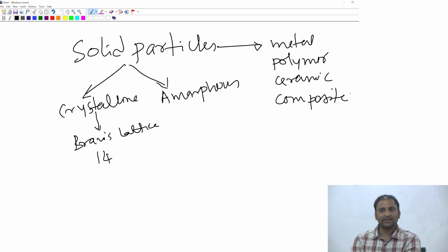Now, is this really important when you're trying to think about fluid particle mechanics? It may or may not. It depends on what kind of fluid particle operations you're trying to do. For example, in powder technology, people worry about making particles by reducing the size. If I have a large particle and I'm reducing its size by some means, maybe hammering it, then I would have to worry about the modulus of the material, because certain types of materials are much easier to break compared to others.